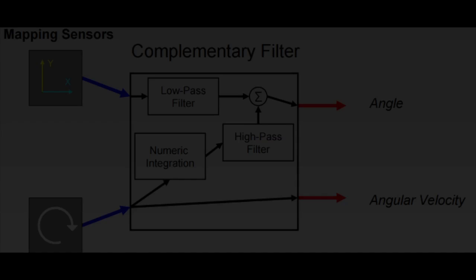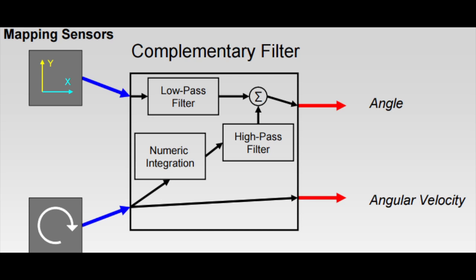and that control value is input into the motors to offset from the neutral value. While this scheme should work on its own, unfortunately we ran into problems with noise coming from our accelerometer. As such, we sought to use the gyroscope, which was integrated into the same sensor, as will be discussed later, to help smooth this out. And to accomplish this, we used a complementary filter.